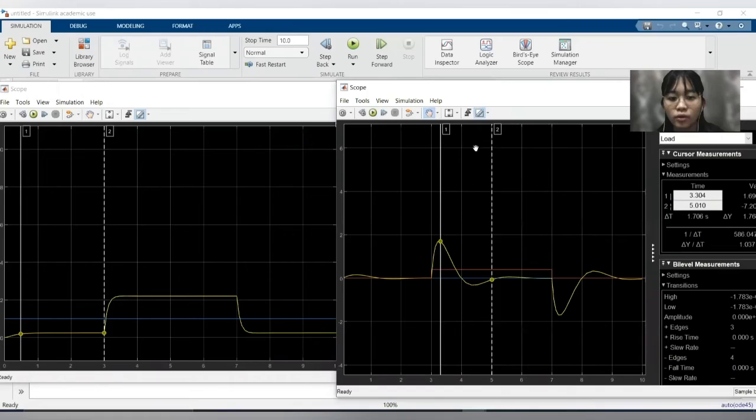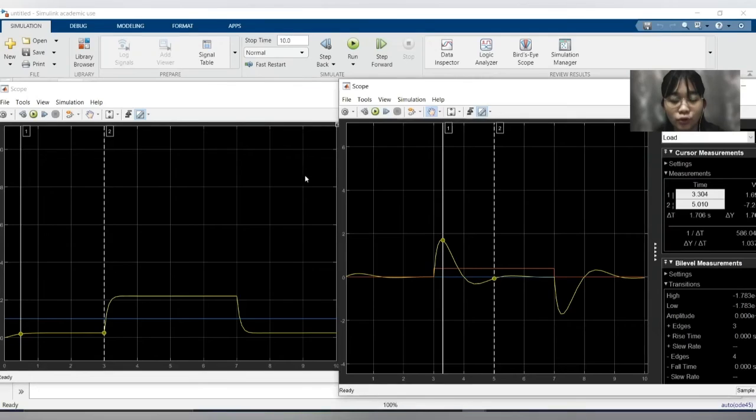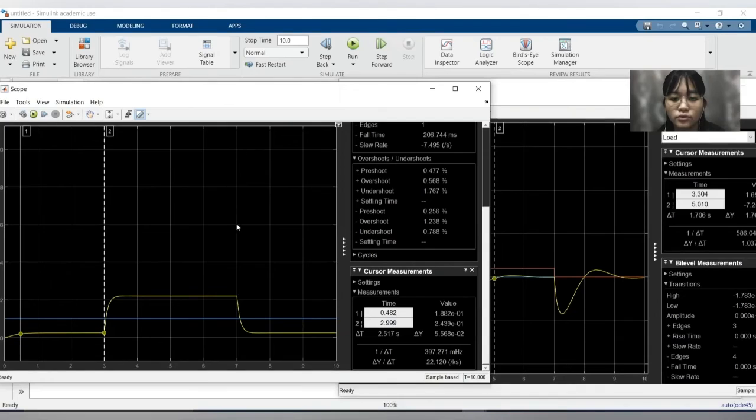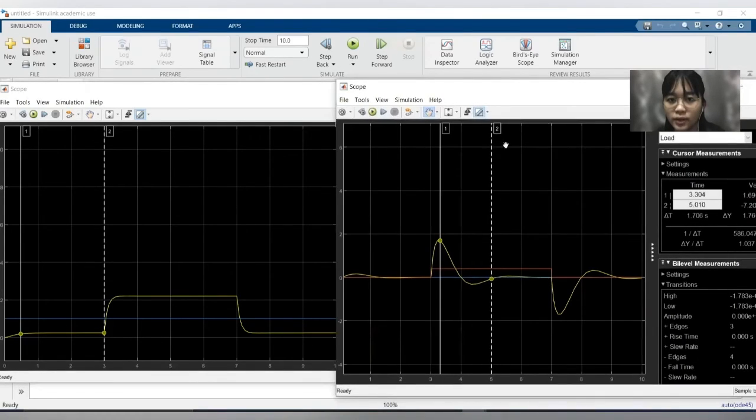A feedback control system is basically a control system where the output depends on the generated feedback signal. We can conclude that the feed forward control system is used to reduce the effect of measurable disturbance, while the feedback system is to trim and compensate for inaccuracy in the process model, measurement error, and unmeasured disturbance.